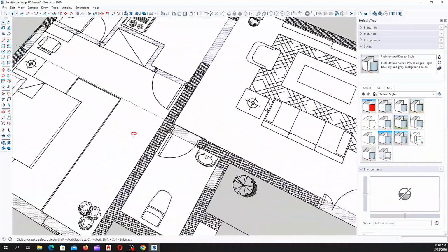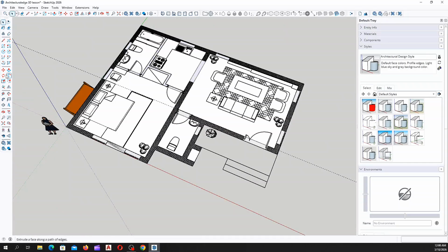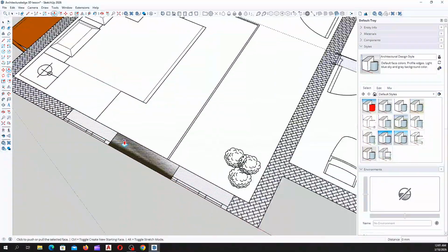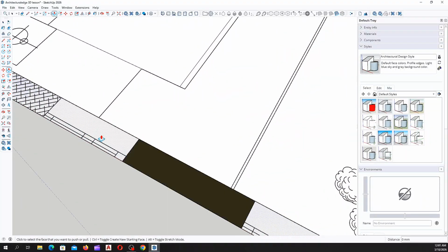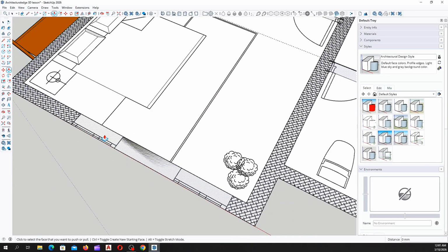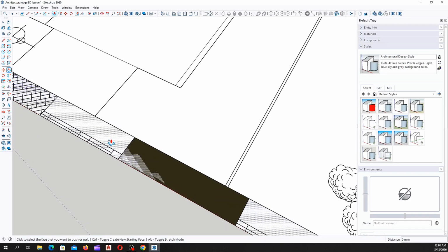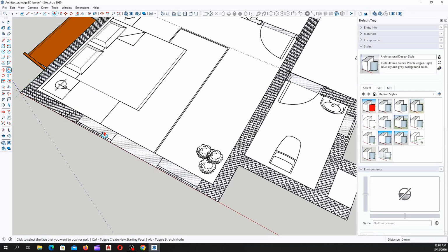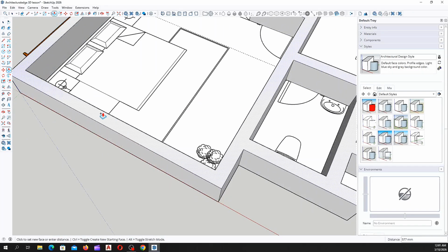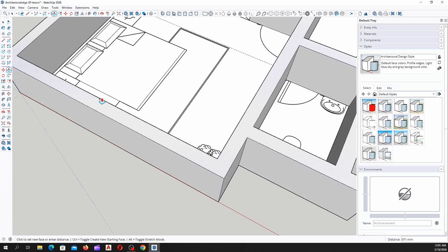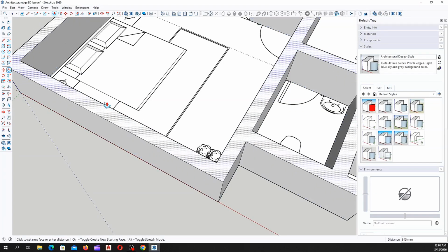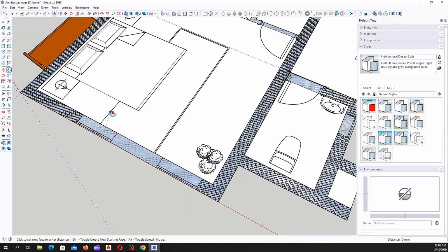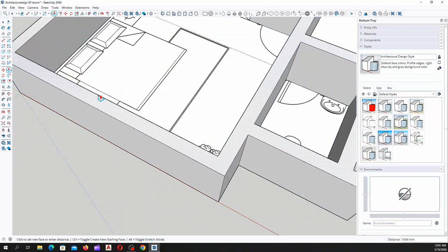So the next thing we are moving into, we are using our push tool. So you come to your floor plan on this area, then you tap your control key. Once you tap your control key, it shows a plus sign at the top of your push tool. So you click on it, then you drag your mouse cursor upward this way, or you tap your up arrow key to lock on the up inference.